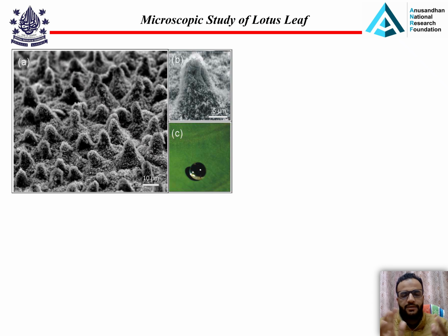These super hydrophobic surfaces, as I mentioned earlier, are inspired from the lotus leaf. If we examine the lotus leaf under a scanning electron microscope, we can see that it is not smooth in nature. It has a rough micro texture, which is further coated with waxy nano structures, and the combination of that micro and nano texture with the low surface energy provided by the waxy coating gives the super hydrophobic property of the lotus leaf.